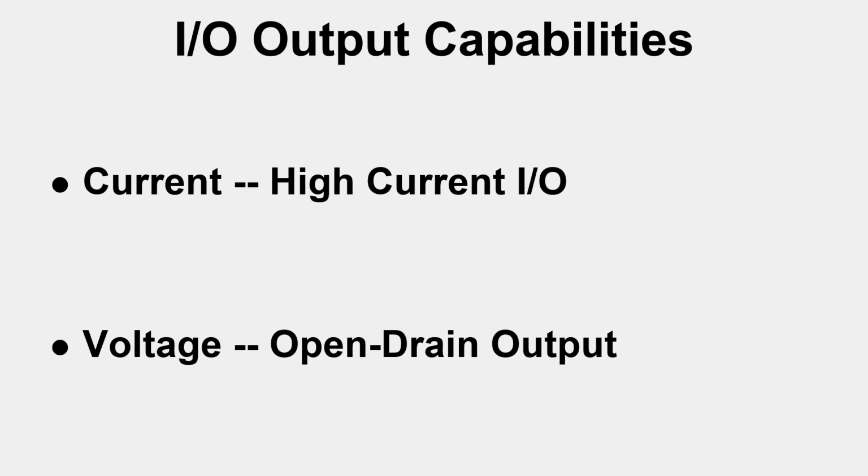So MOSFET is widely used in all kinds of embedded system designs where you essentially use it as a switch. A switch, yeah. Yes, and we have 4 MOSFETs together to form what we call the full bridge to drive things like motors. Okay. Yes. So essentially, you're controlling where current or voltage is inside of a system. Yes. And that's what you're doing when you're driving a FET. Driving something with I/O, the two things are current and voltage, like how much voltage can you reach to drive something.